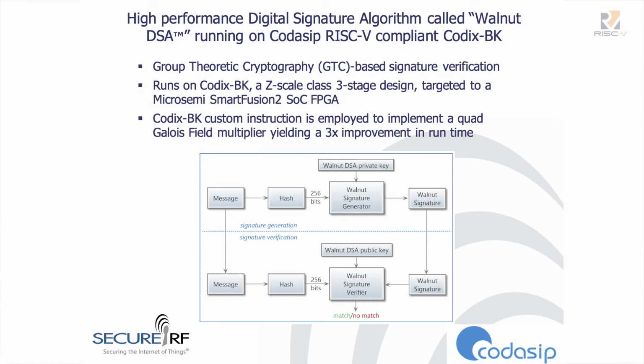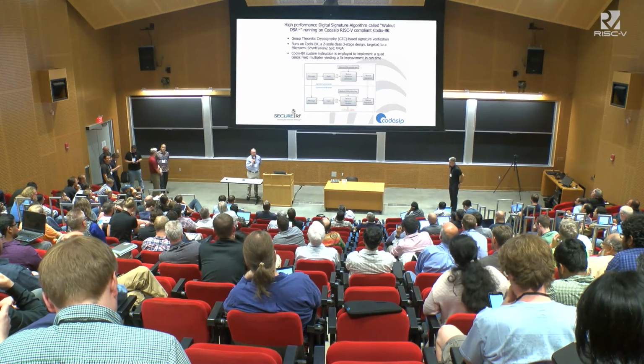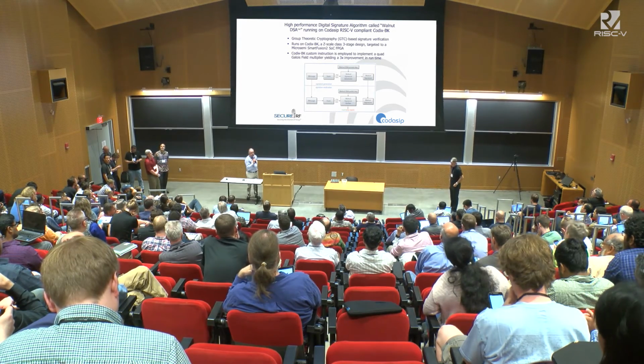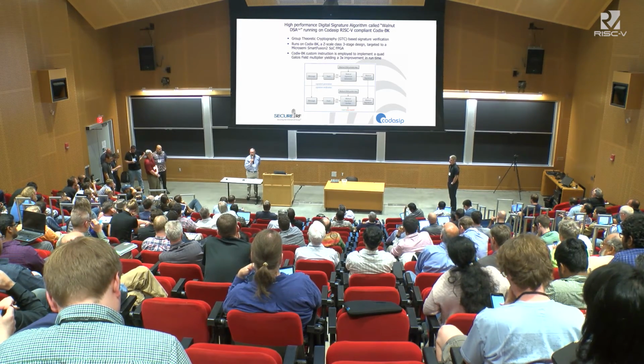Specifically, we target 8 and 16-bit platforms, typically 32-bit, where the standard crypto stuff does not run. A big part of what we do is authentications, and to fill in some blanks from earlier, things like the automotive industry and smart grid, where you need not hundreds but thousands of authentications a second, is one of the places on low resource FPGAs where we do put our methods.